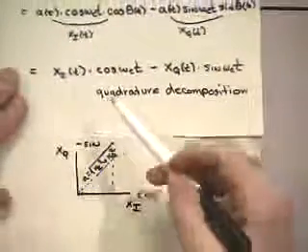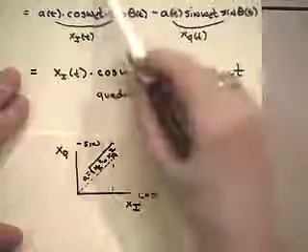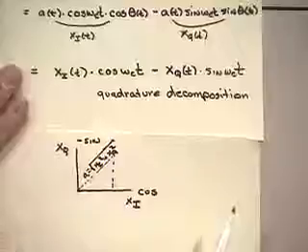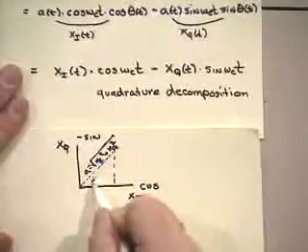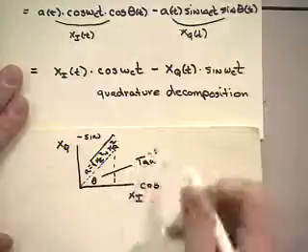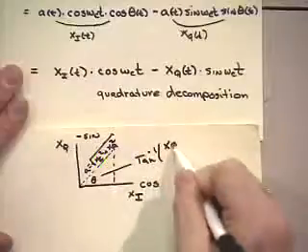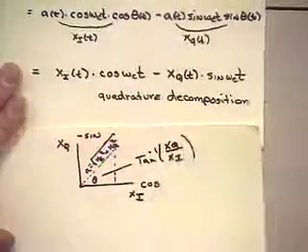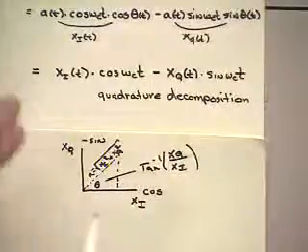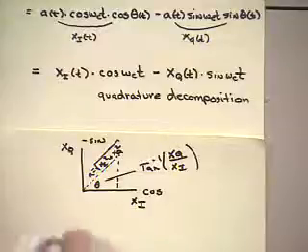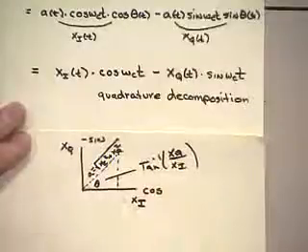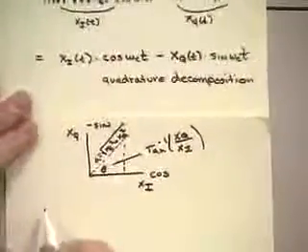And in fact, we could go backwards from this xi and xq, and you would see that a of t is in fact the square root of xi squared plus xq squared. And there's an angle theta here, which is tangent inverse of xq over xi. So we can think of this as some kind of time-varying thing rolling around a circle that's defined by omega ct, some carrier modulated waveform. Kind of nice in this form where we have it decomposed into the two components,